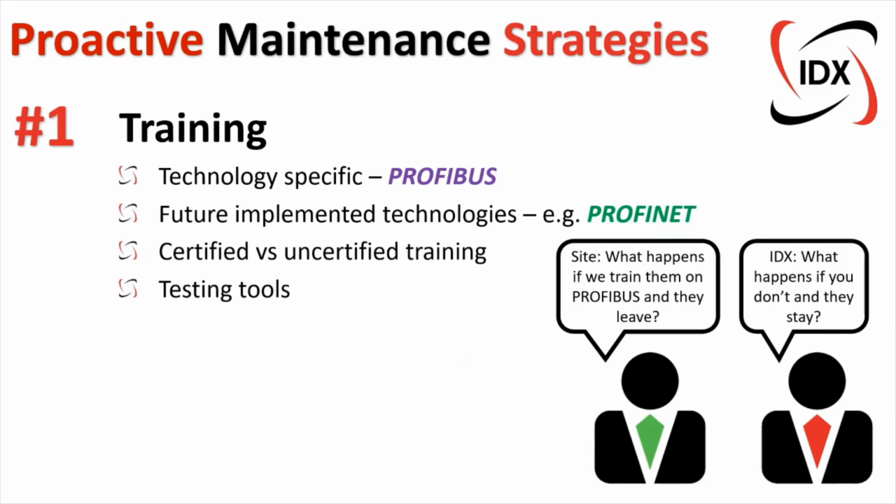Much like that, a PROFIBUS testing tool may unfortunately not assist you in identifying faults and checking the health of your network unless you understand the core principles around PROFIBUS and the PROFIBUS guidelines. The tool will give you statistics and various ways to pick up symptoms within the network. But unless you understand what those symptoms mean, it often will not be as useful as possible.